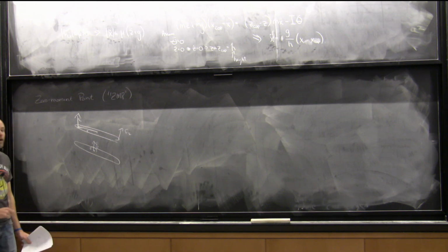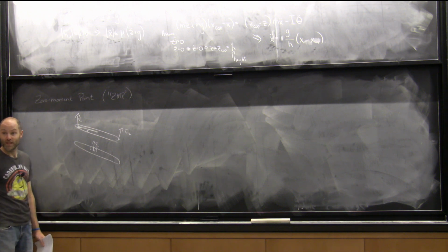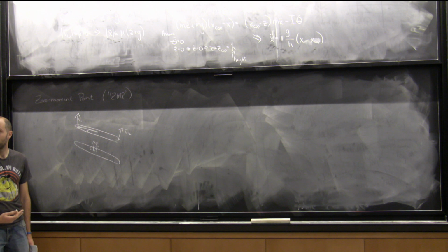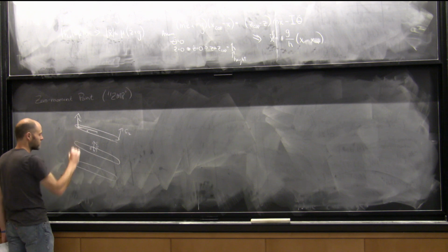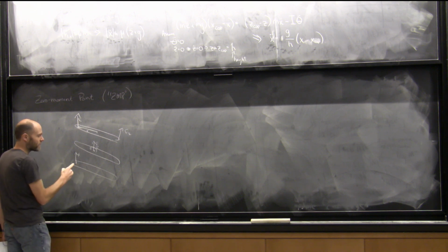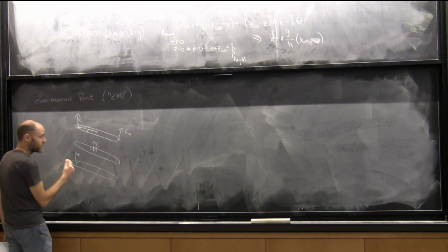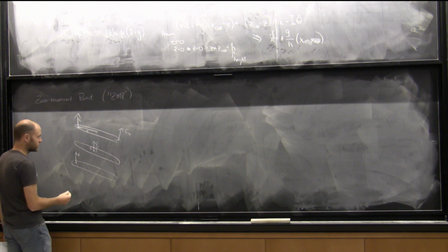Okay? There are a few points out there, maybe typically a line of points if you're working in 2D, where the torque that is required to summarize it is 0. So there might be some special points. For instance, if I only have a single force acting on the body, that's an easy case where that would be my zero moment point. But even if I have a bunch of forces, there's some summarization point where the way that I describe the influence of those forces on the body, around that point, is just a force and no torque, right?